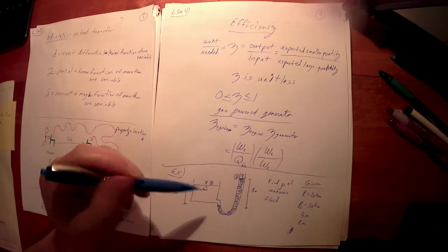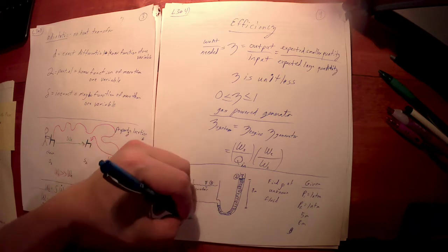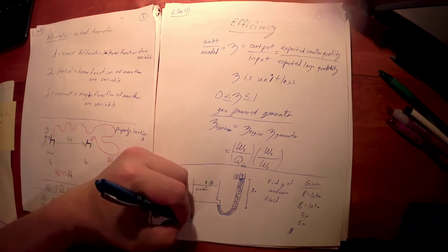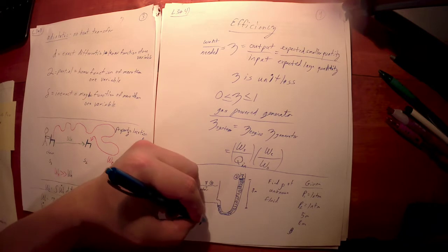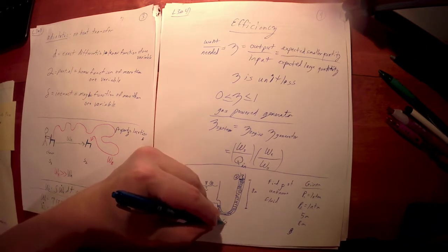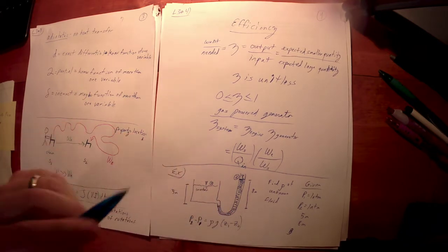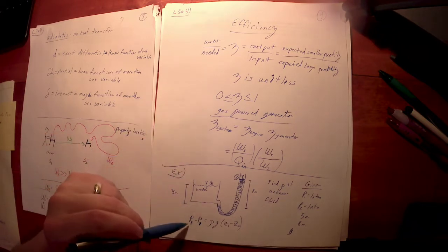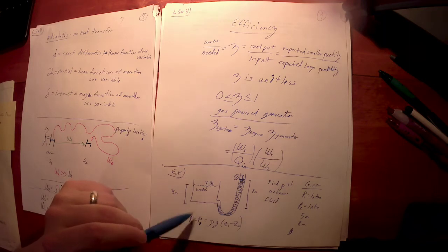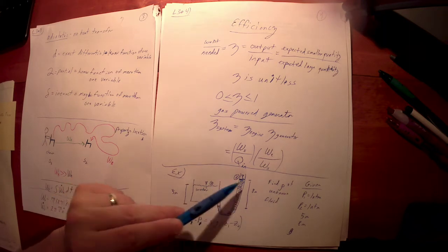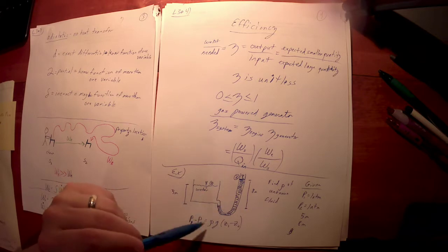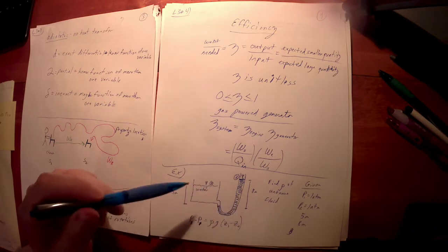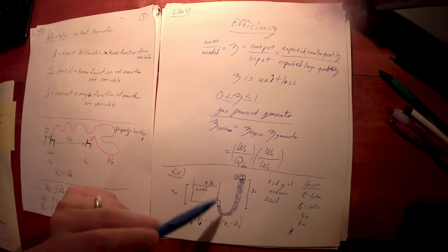Well, I do know that it shows up as a variable in this expression, which we wrote this way. We derived it as P2 minus P1 is equal to the density times gravity times Z1 minus Z2. Now, here's the thing. We derived this for the pressure between location 1 and 2 for the same fluid between those two. Here I've got something different. This equation wasn't derived for this scenario. So I'm going to have to change some things.